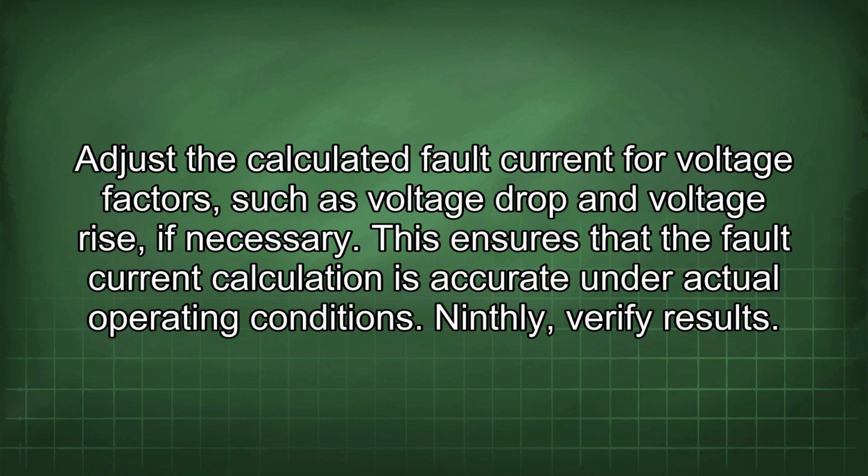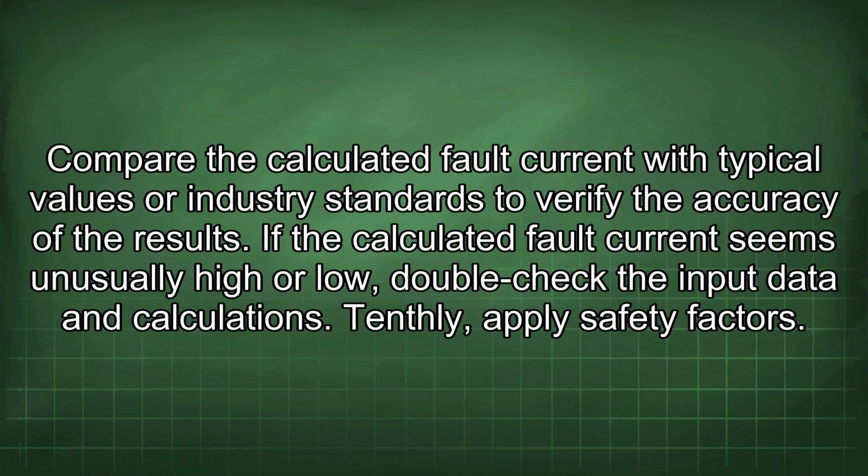Ninthly, verify results. Compare the calculated fault current with typical values or industry standards to verify the accuracy of the results. If the calculated fault current seems unusually high or low, double-check the input data and calculations.